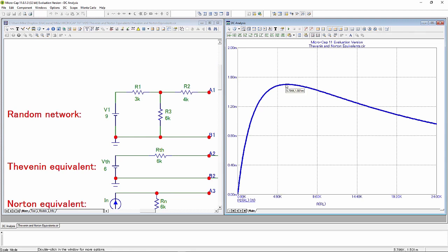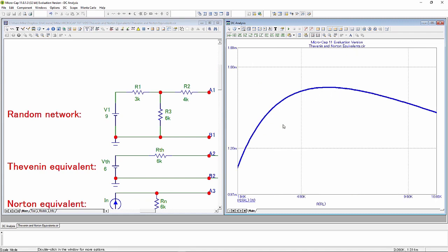That's what it's saying. It's quite difficult to tell. You can zoom in, I suppose. Let me try zooming in on there. Then go up here some, 5.9888, so very close to 6. Here we are, that point there. And that's the point of maximum power transfer. So we got around about 1.5 milliwatts of power transfer to RL at that point.